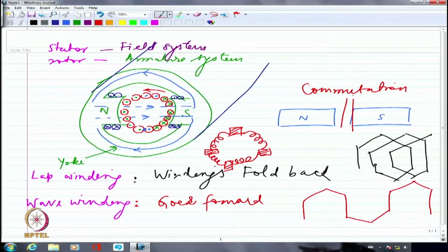So if it is a 4-pole machine, for example, this is going to be plus, which is affiliated to North Pole. This will also be plus, this will be minus, and this will be minus as well. And just to make sure that the two pluses are not at different voltages, normally they will be short circuited externally with thick copper conductors.